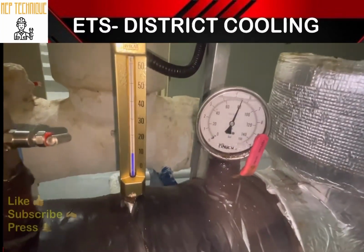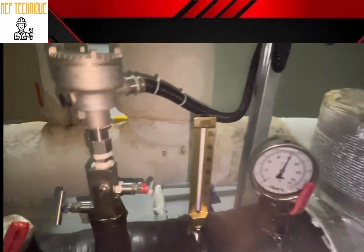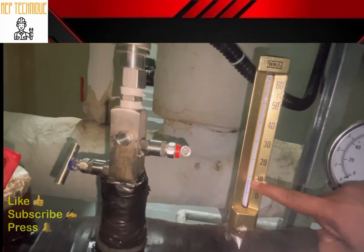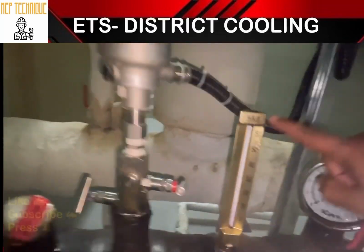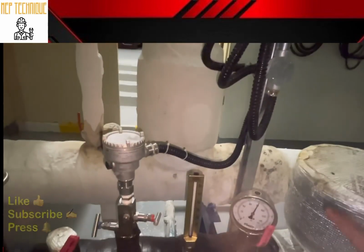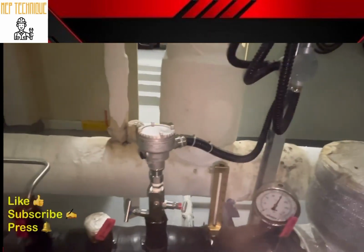It is showing 80 psi now, and this is the temperature gauge showing the chilled water supply temperature. You can see here, this is below 10. So this is the temperature gauge and the pressure gauge. Every day you need to check these to make sure your ETS is in normal condition.